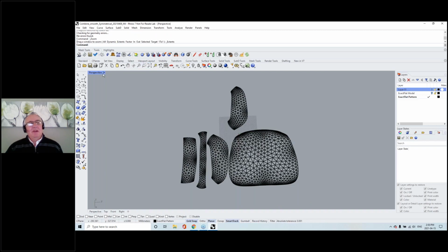And I'm going to shade it because ExactFlat runs like an FEA analysis, and it's going to show the strain on the seat or on the headrest. So once I turn this on, you can see the strain on the edges. Now, ExactFlat's a two-step flattener. The first step gives us what we call a projected flat, and that's what we're looking at now. The second step's when I go in and I optimize. So I'm going to select the material that the headrest is made out of and flatten based on that material type. And that's one of the things that makes this flattener so unique and so accurate, is that you actually can address the material properties. So if this was a leather headrest, it's going to flatten the material as if it was leather. If it was a nylon, I'd flatten it based on how nylon flattens.